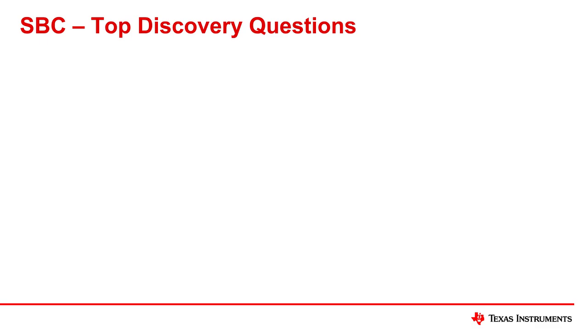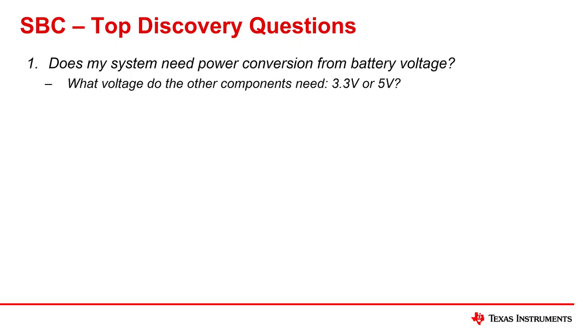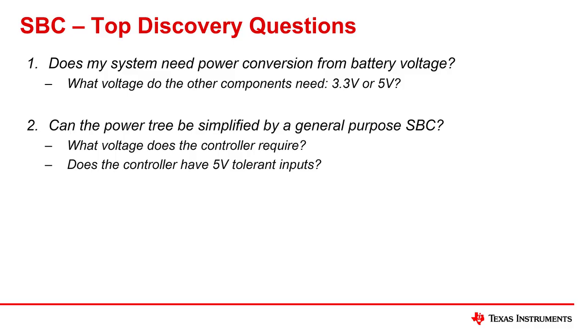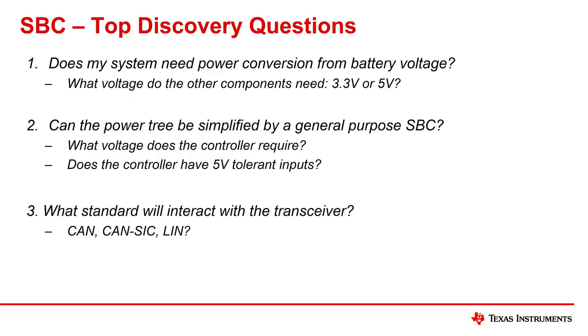Yet to determine if an application will benefit from the integration of an SBC, and to pre-select the SBC, here are the top 3 questions that any designer should consider when looking at their system. Does the system need bus communication and power conversion from battery voltage? Can the power tree be simplified by a general-purpose SBC, i.e., what voltage does the controller require, and does the controller have 5-volt tolerant inputs? What standard is used for communication? Is it CAN SIC or is it LIN?